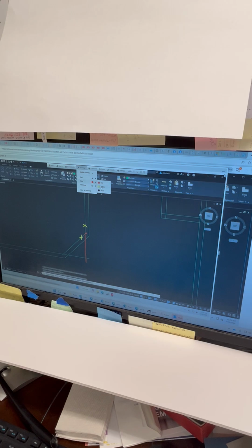Similarly, over here, you're going to pick on this portion you want to keep. And by the way, it does not have to be this close. I mean, I could pick anywhere along this line, just as long as I don't pick here or here, because that's the opposite of what you're trying to do. My students think that this is the trim command, and you pick on those portions you want to trim. That's not it. You want to pick on the parts you want to keep, and therefore it's going to get rid of this portion.